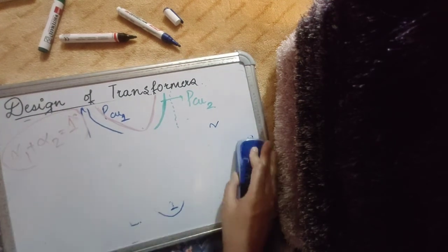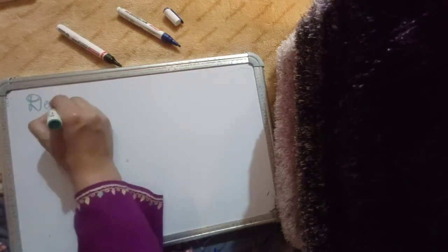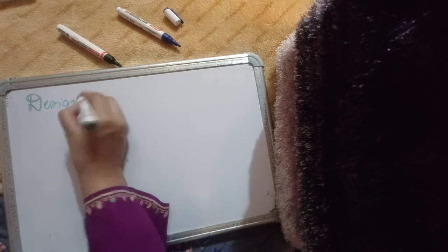I'll briefly go through capacitor design, because as you all know, the capacitors don't have to be really designed. You have to purchase them from the market. The only thing that you have to do while designing a capacitor is to choose the value of the capacitor and its voltage rating. So we have already discussed the design of capacitors in the last semester when we were doing applied power electronics for DC to DC converters.